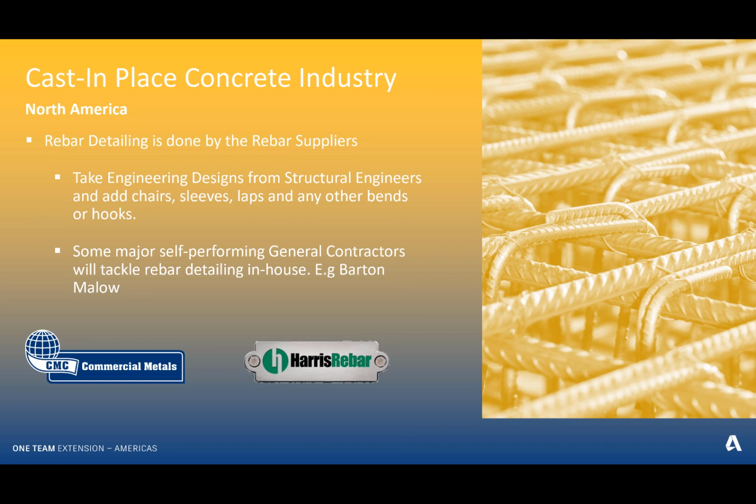And then the rebar detailing. This one actually has been a pretty big focus for Autodesk within Revit for the past few years. Not just through generating detailing rebar and saying, okay, yes, I have a rebar set or varying rebar, but now it's integrating that generative design into that rebar. If I have a ramp that's following my parking garage and I know it's all precast, if I want to run bar through that, I can just pick my host surface, tell it the start, the end, what shape of bar I want to use and what type of spacing I'm looking at, or if I want to specify, and it'll run it through there, the whole thing for me, okay? It'll follow the shape of the concrete and everything. It's pretty fantastic.